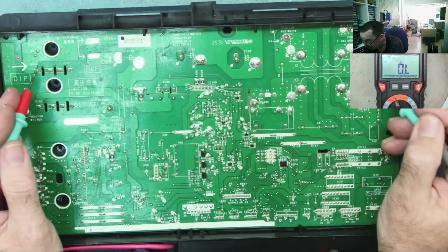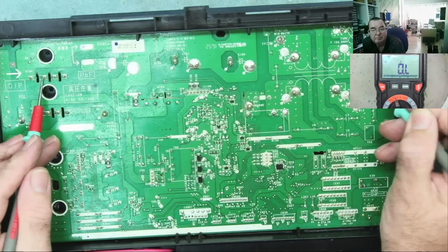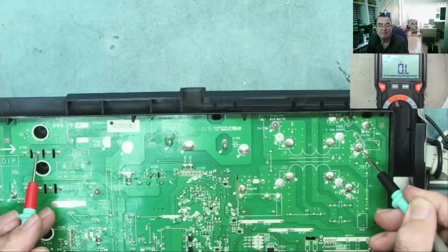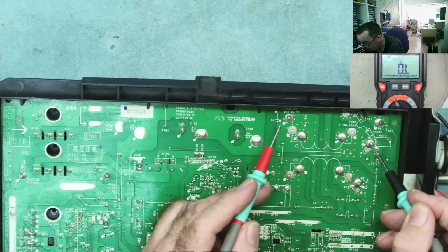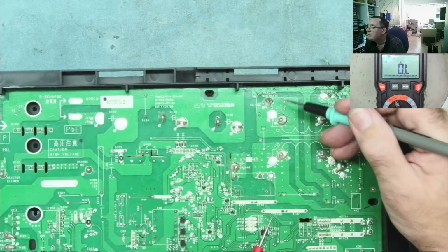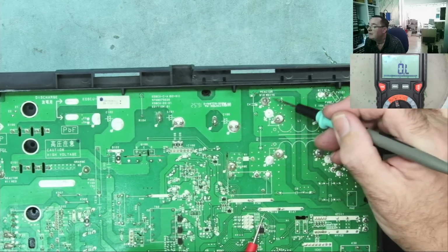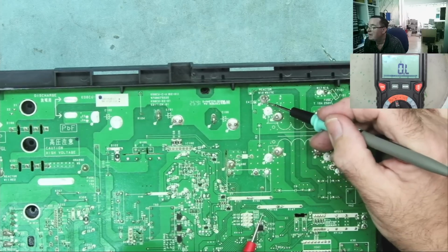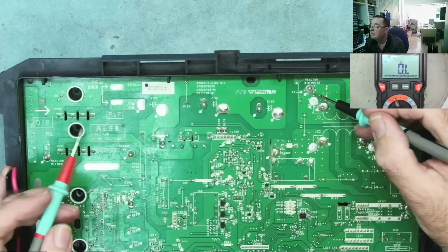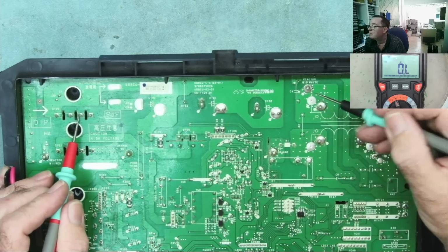Okay? And the other AC input you'll see doesn't go to the bridge rectifier, not directly anyway. Yeah, there's nothing there. That goes here, and then it goes to where it says here, reactor white. So something connects to there and then it must come back on another wire.